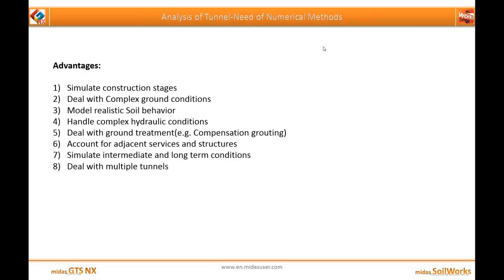So what are the advantages one gets with the numerical methods? First of all, you can simulate the construction stages, that is you can simulate the actual ground sequence in your model. Second, you can deal with complex ground conditions. Third, you can model realistic soil behavior. Fourthly, you can handle complex hydraulic conditions. Also, you can deal with different ground treatments, for example, compensation grouting.